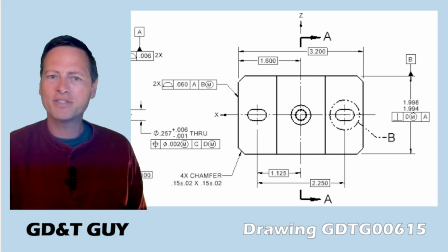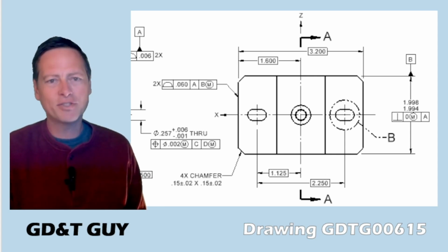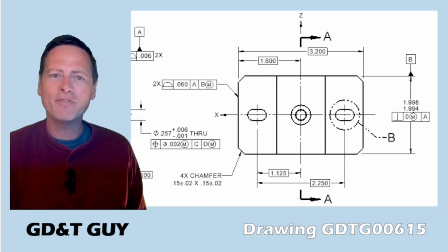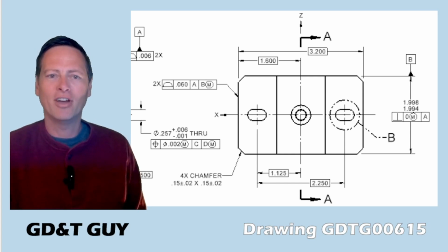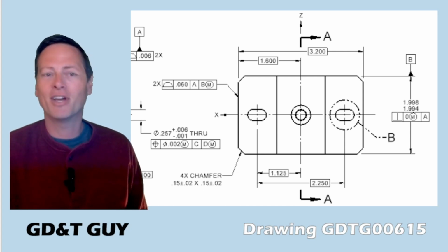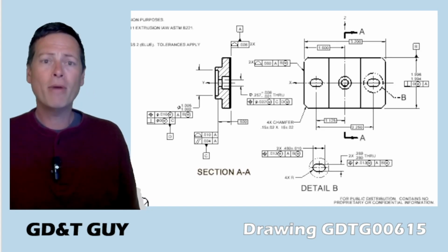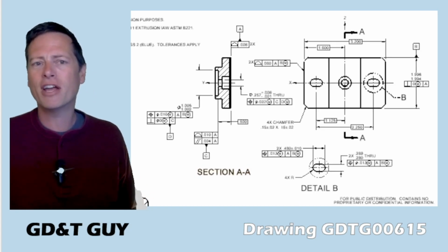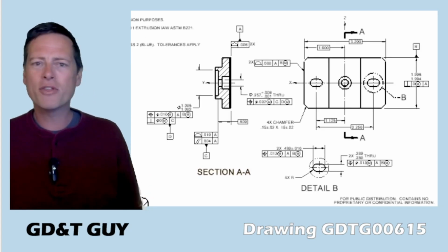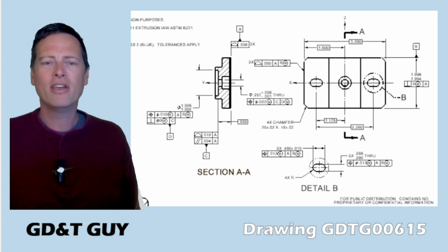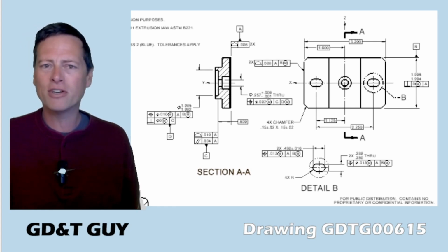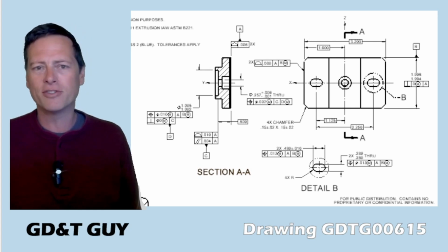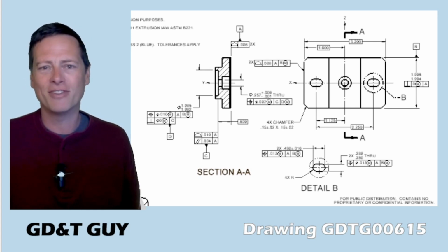This drawing treats those left and right ends as loose tolerance features, the kind of features that on a more complex part might just fall under the so-called unless otherwise specified profile tolerance that we see on drawings pretty often these days. My point was that this could be preferable to trying to force one of these ends or the center plane of the 3-inch width into being a tertiary datum feature used to locate the screw clearance holes or the 1-inch diameter feature.